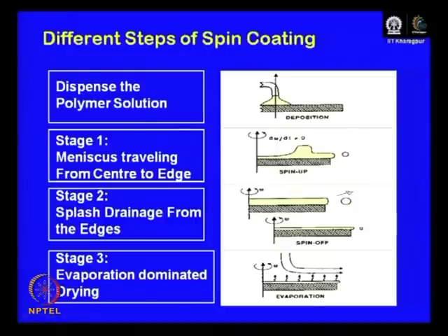On the other hand, if you use a solvent that evaporates too slowly, or you have an environment which is pre-saturated or partially saturated with vapor pressure of solvent molecules that affect the solvent evaporation rate, what might happen is that the level of the residual solvent, even after spin coating, might be too high.